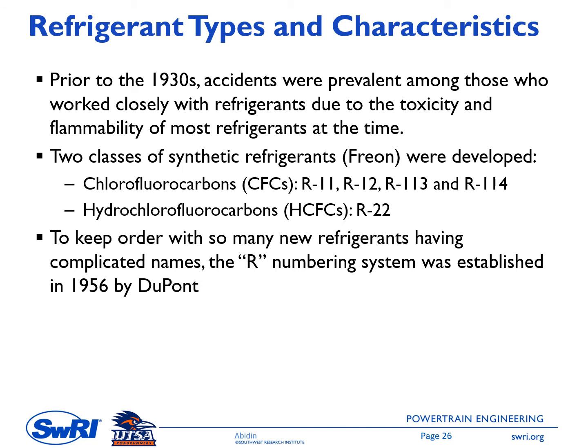One is from the class of chlorofluorocarbon, CFC, and in this class we have R11, R12, R113, and R114. The second class is called hydrochlorofluorocarbon, HCFC, and in this class we have R22.